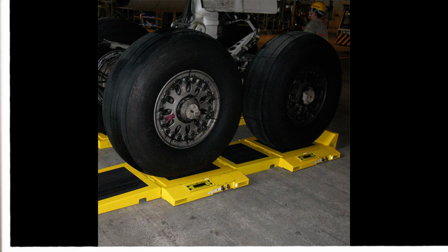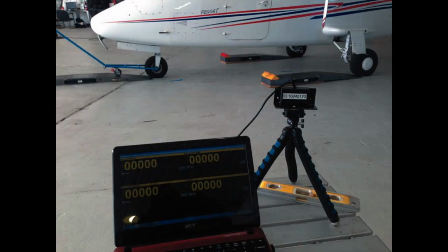Weigh clean aircraft inside hangar. The aircraft should be weighed inside a hangar where wind cannot blow over the surface and cause fluctuating or false scale readings. The aircraft should be clean inside and out, with special attention paid to the bilge area to ensure that no water or debris is trapped there. The outside of the aircraft should be as free as possible of all mud and dirt.